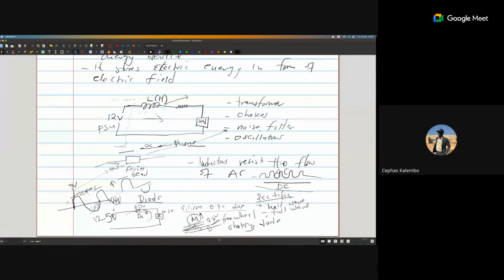If you install this solar panel at your house or in your laboratory, or wherever you are working, and for some reason there's a shade on this particular solar panel, whether you have put a cap, you haven't put it nicely, or if you have installed it on the house, the tree casts a shade on just one single cell. The resistance in this single cell will be so high that the total cumulative voltage up to this point might be so low, such as maybe you can even just get 0.5 volts at the end instead of 2 volts.